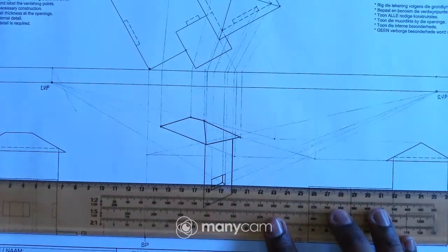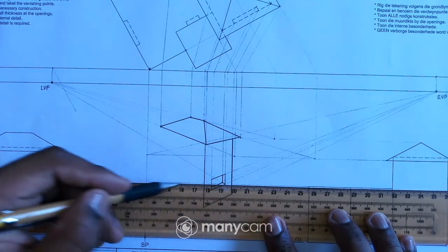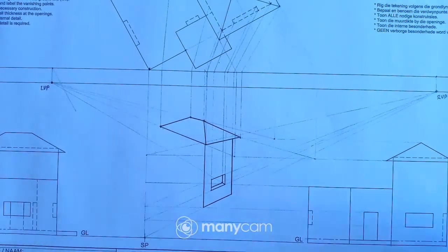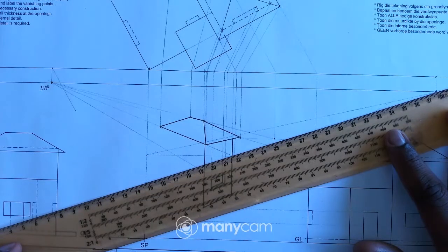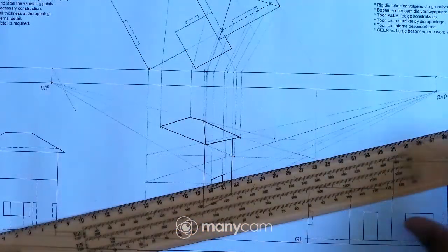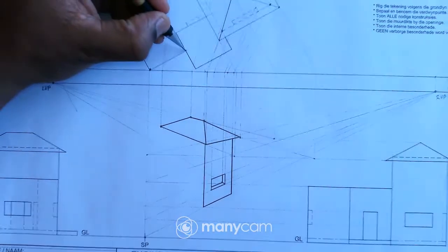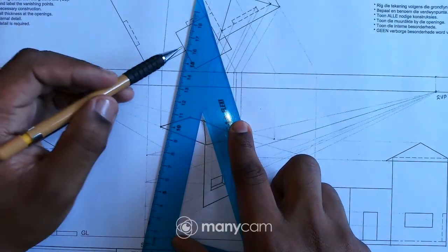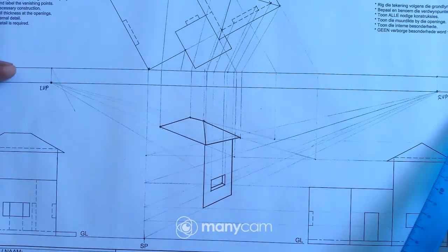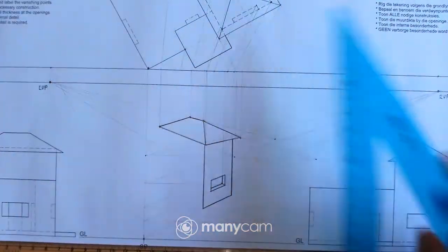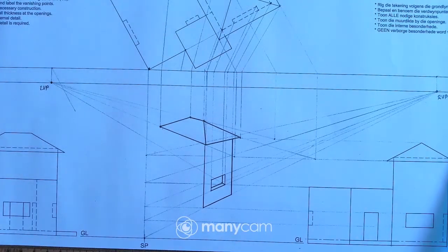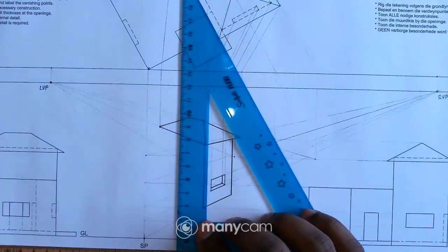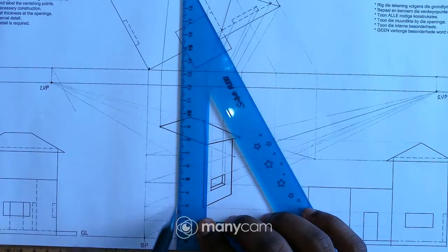So I'll have to project first the height of that part of the building to this line. Okay, from there I'll just take this line to my right vanishing point, like that. And then obviously this point I'll have to take it to the station point, because that point is not on the picture plane. So all the points that are on the picture plane, you just drop them down. So because that point is not on the picture plane, that means I'll have to project this point first to the station point, then I drop it down. So from there I'll just draw a vertical line.